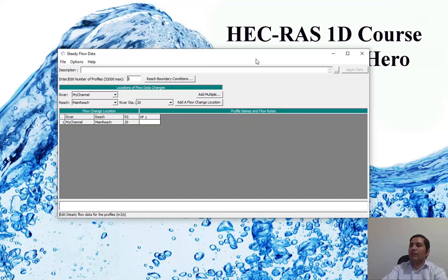and in this window you should define the number and the value of flow values. You know, HEC-RAS can simulate about 3000 water surface profiles simultaneously, but in this section, we want to enter 3 different flows and simulate the hydraulic property.